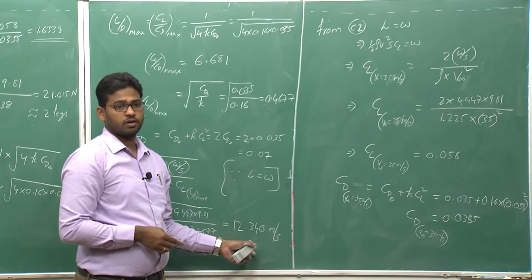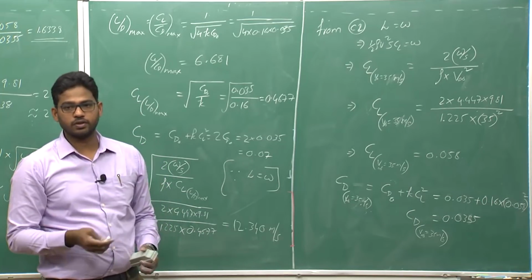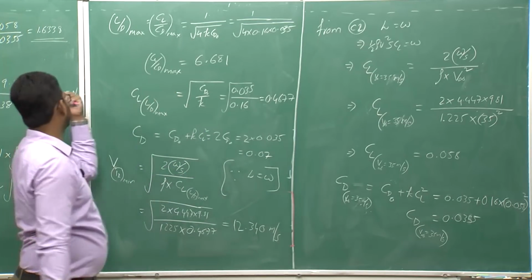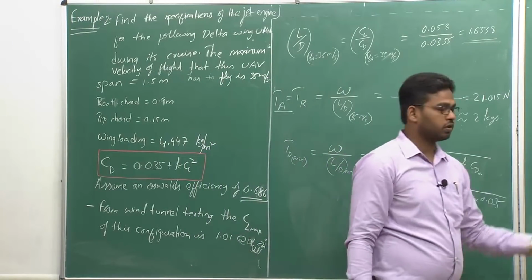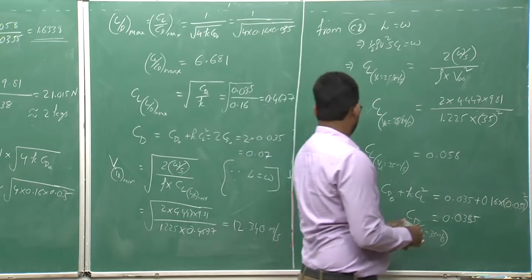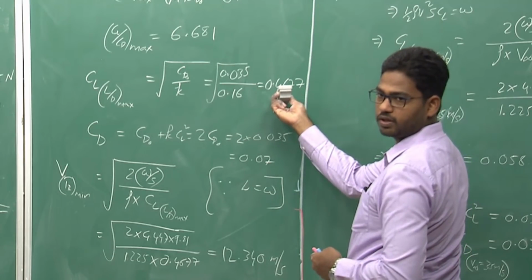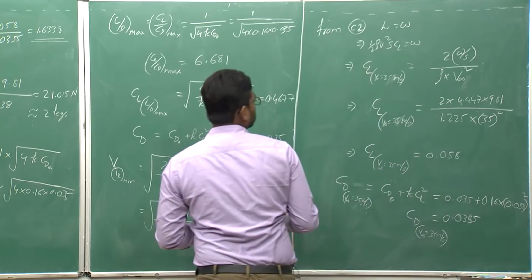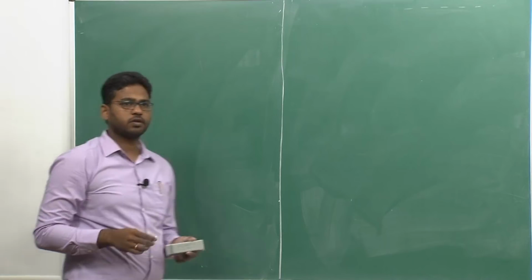So, this is your boundary for stable flight, the velocity regime for stable flight. This is the minimum limit. The maximum limit that you already specified as per the mission requirements is 35 meters per second. So, you have a velocity range of 12 to 35 meters per second using this jet aircraft, right. See, as the velocity decreases, the corresponding CL value has increased here, right. Here the CL value is very less, but the velocity is high. So, the profile drag is higher, that is why L by D is lesser. Let us look at another example.